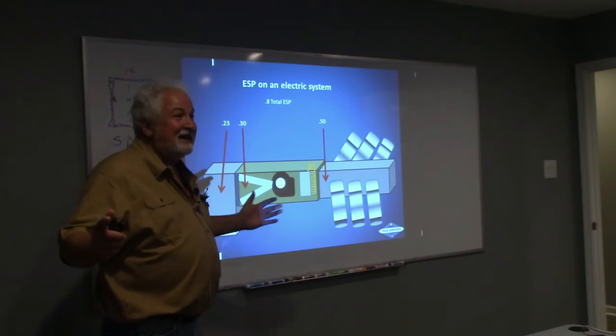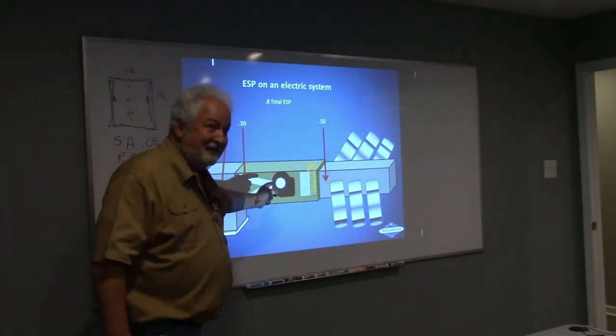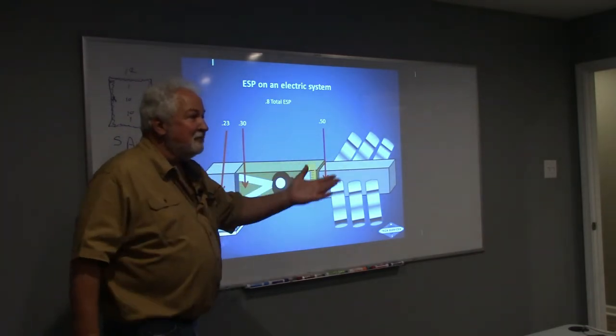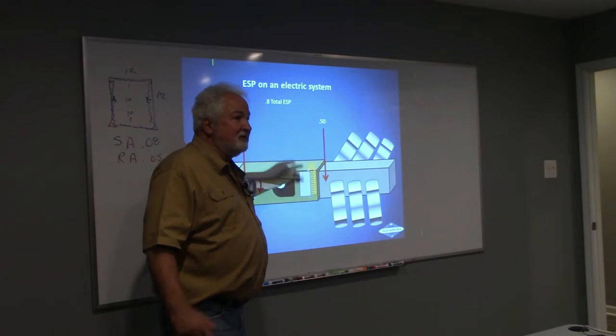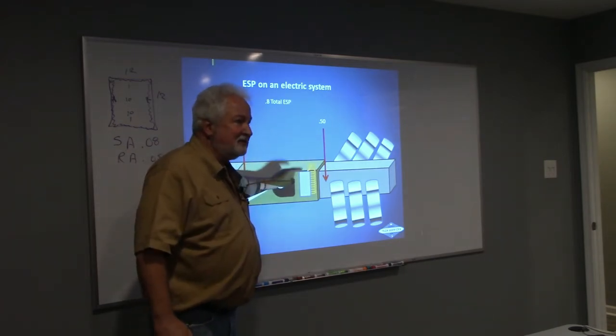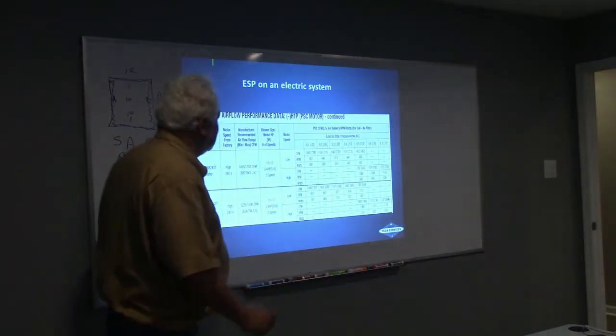Look, as long as it's there, I still have the opportunity to go look. Is that right? Good. So what I'm going to tell you is every time you start up a unit, I need the blower external static written on there, so now everybody knows that this is what we started with. This system started off with this much resistance. Is that fair? Cool. All right, so we're going to roll it.